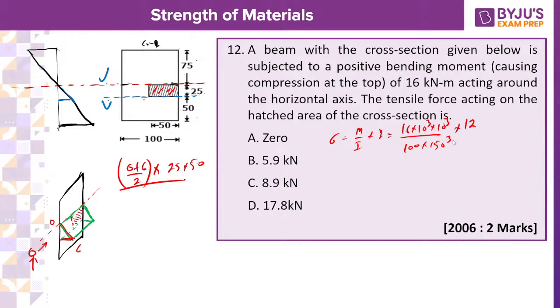And what is your y? Actually, I am interested in the bending stress at this location. So what is my y value from the neutral axis? That is 25, so multiply with 25, isn't it? And after multiplication and all the calculation, you will get around 14.22 Newton per mm square. That is the bending stress.